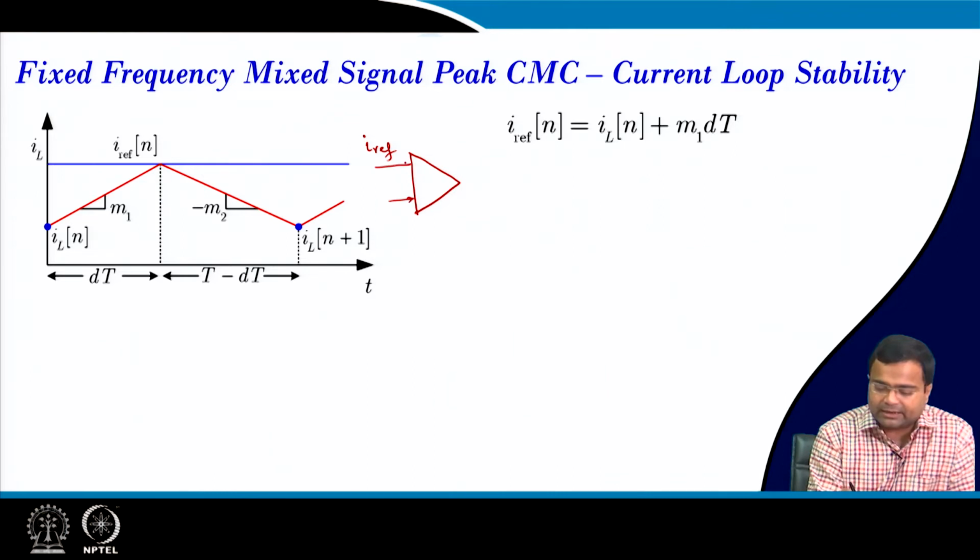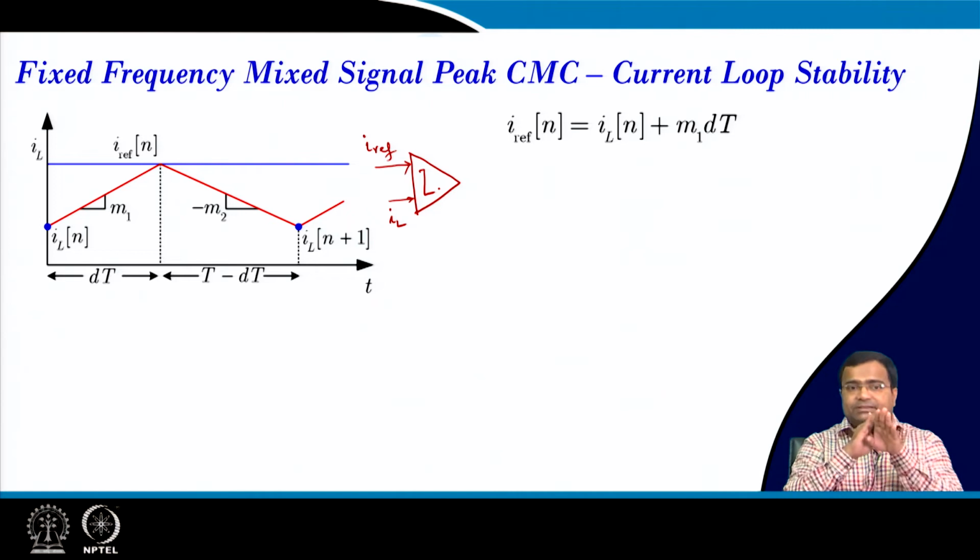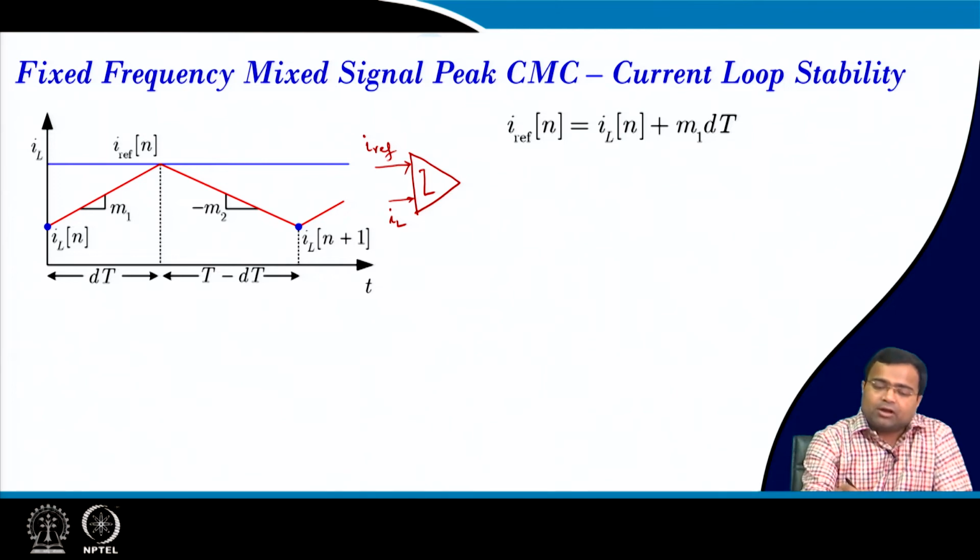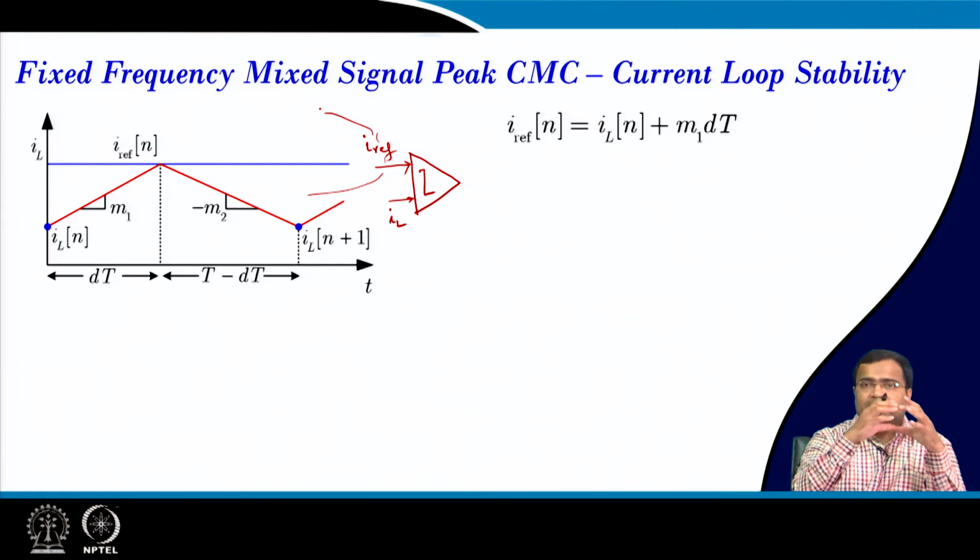and the inductor current are in analog. So, one can expect for the same reference current, the mixed signal inner loop stability, that means the 0 input stability, must be identical, and that is because they are identical in terms of analog current loop. Only the digital part will come here, when the mixed signal will have a digital compensator followed by a D2A converter, that we have seen. After that, the IREF is in analog and all the current loop, comparator, latch circuit are in analog, which is identical to analog current mode control.